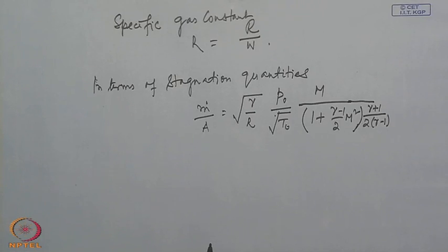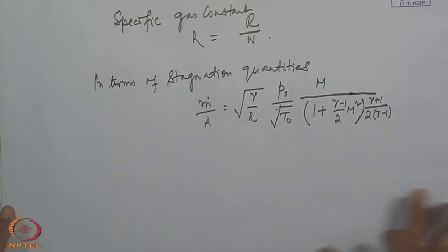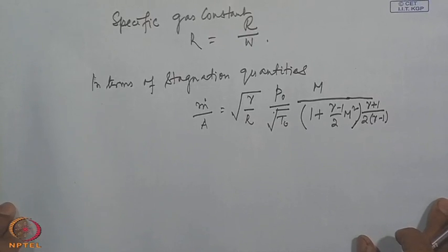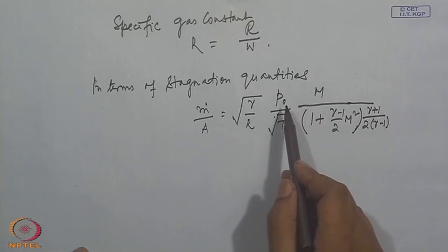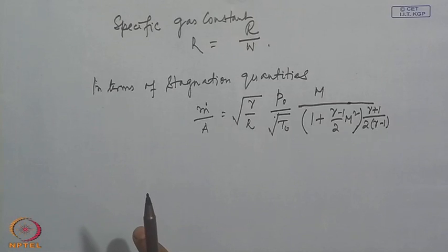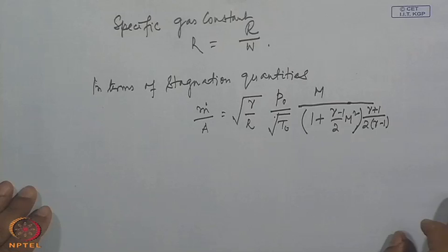However, there is no friction or viscous effect and there is no heat addition or heat transfer, and since this is adiabatic frictionless flow, the flow is essentially isentropic and the entropy remains constant everywhere, and consequently the stagnation quantities P 0 and T 0 are also constant throughout. And also we have seen earlier that in an isentropic flow the sonic condition is constant, that is A star is also constant throughout.